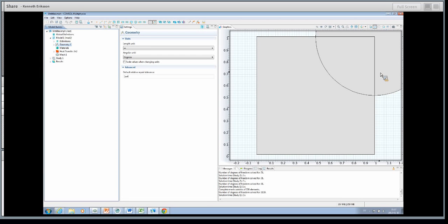And then I press the control button and left click the mouse on the circle to make two choices. And then I go up to the menu here where we have the difference operation. We take the square area minus the circular area. So I left click this, and then the circular part of the square disappeared. So this is now my domain, and you could of course easily do all kinds of operations using these options here.